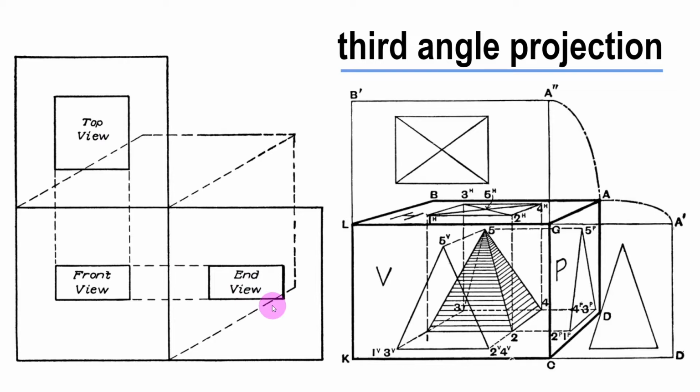In first angle projection, which a lot of the rest of the world uses, they use the front view with a top view above it and then a side view projected over here. So they'll use the left side where we typically use the right side. But we just have our different faces of our object projected onto the different planes, so that way it's two-dimensional.